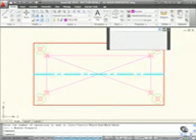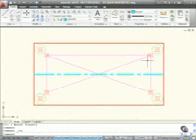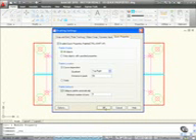Now what happens is as soon as I click on that customize, it takes a few seconds, but it actually brings up the Customize User Interface dialog, allowing me to edit settings within AutoCAD itself. So I've even got that option to work with when I've got Quick Properties switched on. So again, it's very easy. QP down here, right click and settings, set your settings and OK them.